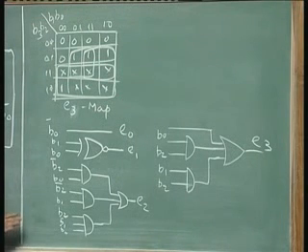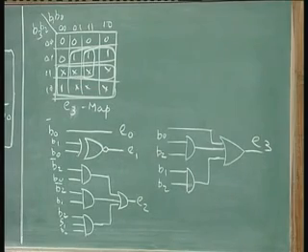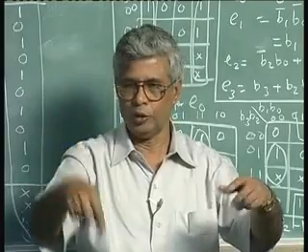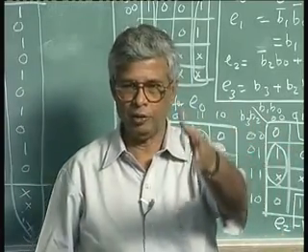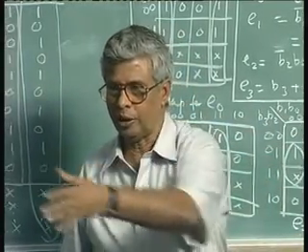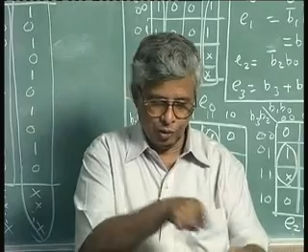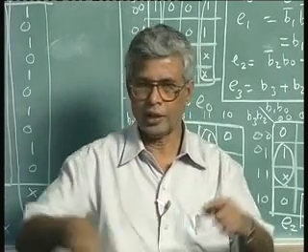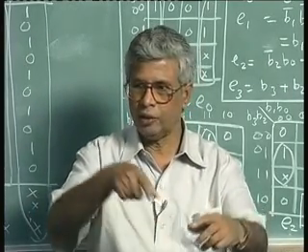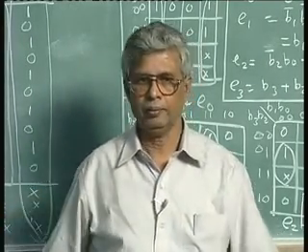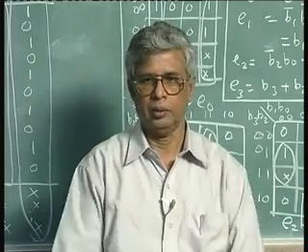You represent it like this, a solid. When you wire it up, of course, there's B0, B1, B2, B3 coming into a circuit, and you have to get them inverted if you want: B0 bar, B1 bar, B2 bar, B3 bar. So you will have 8: B0, B0 bar, B1, B1 bar, B2, B2 bar, B3, B3 bar. Then you have all these gates, wire them up, crisscross, and then get E0, E1, E2, E3. Then the circuit is built.